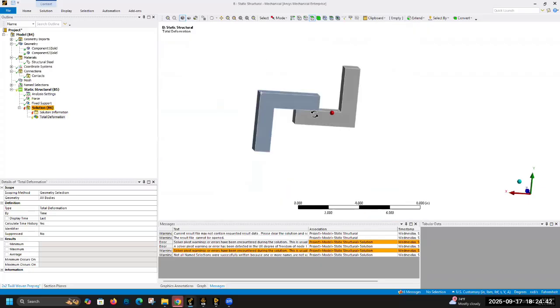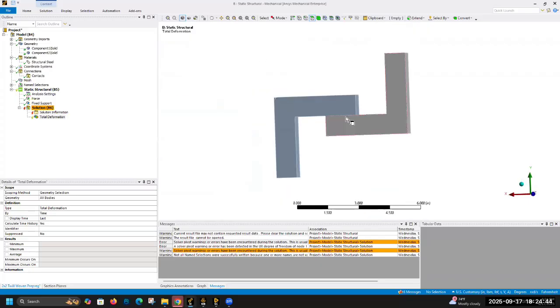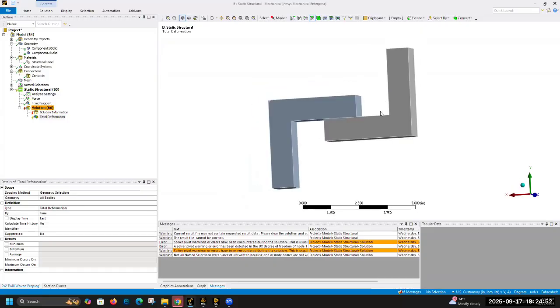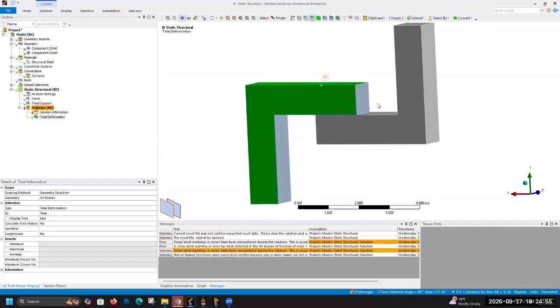And so the key thing here is, we're not running a dynamic sim, right? So we're not simulating dynamics, we're simulating static structural. So key point there is it should be static, and this model is not static, so it's ill-constrained.